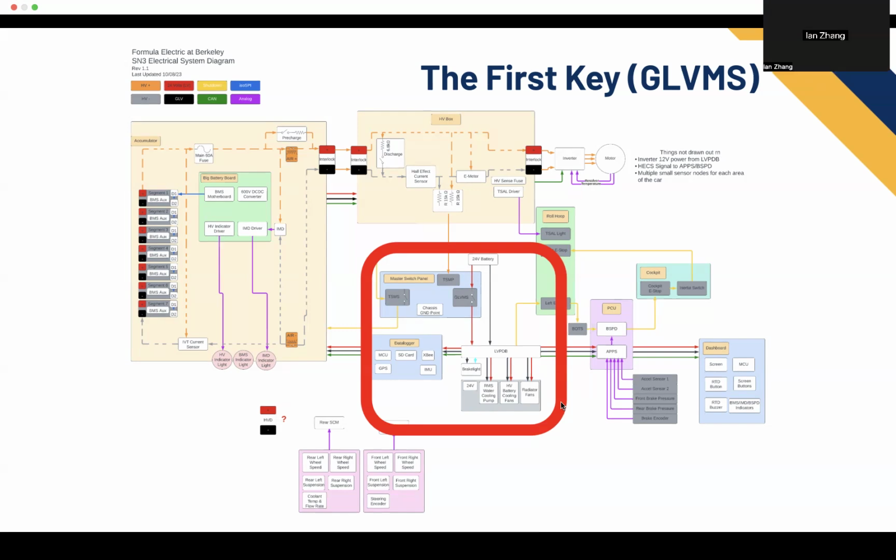Yeah. Hey, Andrew. I'm supposed to be working on the brake light, and you said that turning the brake light on and off is controlled by the CAN bus. When I'm designing the circuit, first of all, I have 24 volts powering the board, right? But then do I need to have an STM32 on that as well to receive CAN messages and turn on and off the brake light, or how exactly does that work?